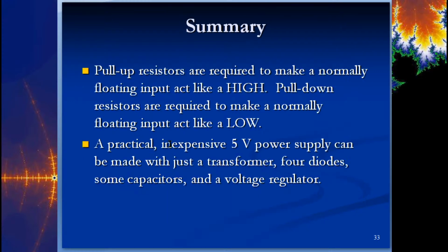And we talked about pull-up resistors versus pull-down resistors. If you want to force something high or force something low, those are what you would use. We used a 10K for a pull-up and a 100 ohm for a pull-down. And we also went over the practical, inexpensive 5-volt power supply that can be made with a transformer.